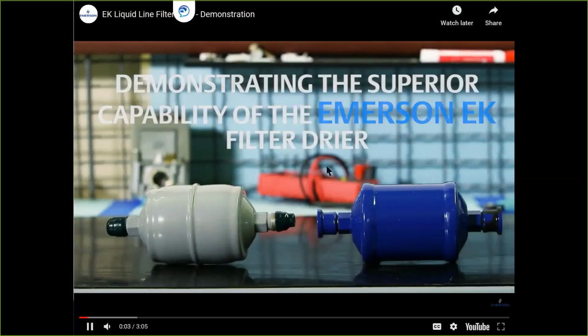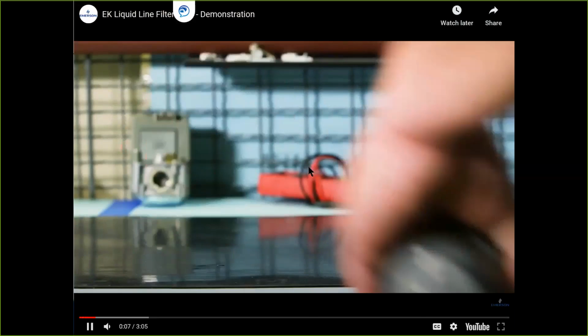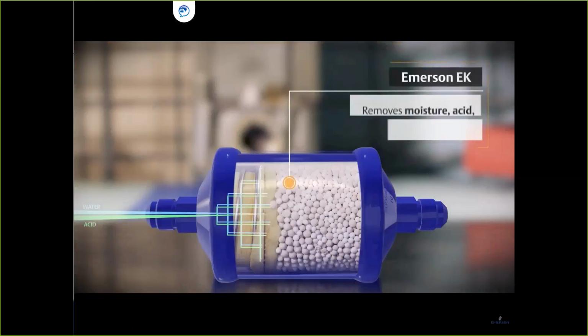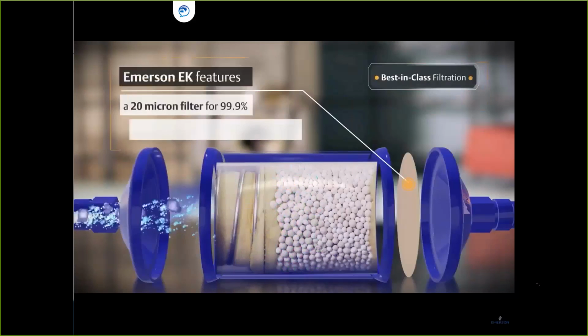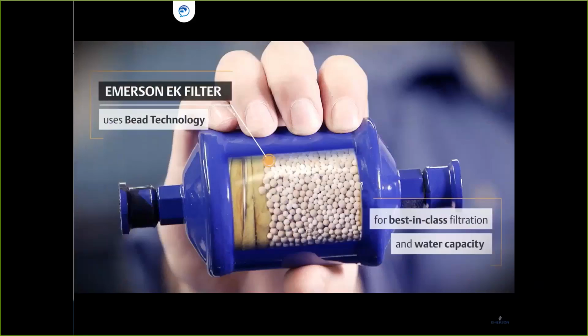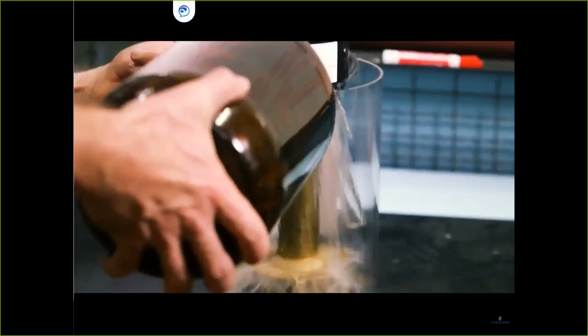This demonstration, we're going to prove that not all filter dryers are equal. The three main functions of a filter dryer in a refrigeration or air conditioning system are to remove moisture, remove acid, and to remove solid particles. The Emerson EK filter dryer has a compacted bead construction which features best-in-class filtration. This demonstration closely replicates the ASHRAE procedure for testing liquid-line filter dryer filtration.